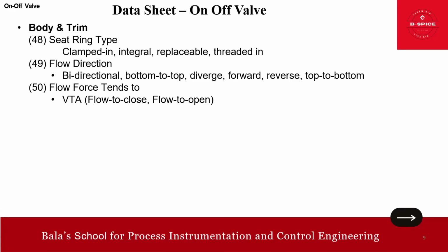Maybe I'll give just an example, friends, for flow to close. Imagine a drain plug in a bathtub. The flow direction is against the back or top of the plug rather than the face, right? It's not the face. So it's creating a tendency for the plug to close into the drain. So in valves, similarly, this means the fluid flows over the plug, resulting in a closing action.